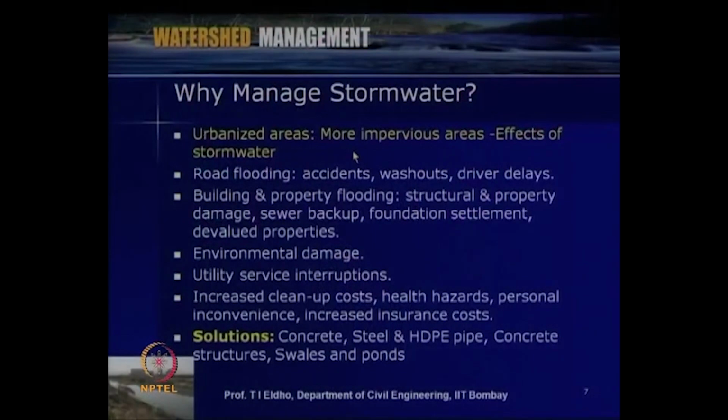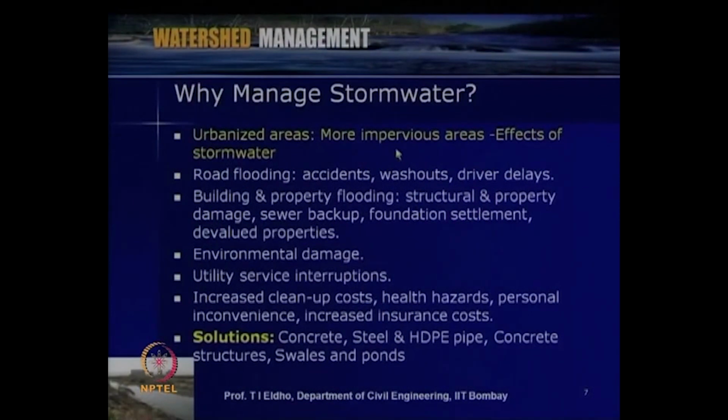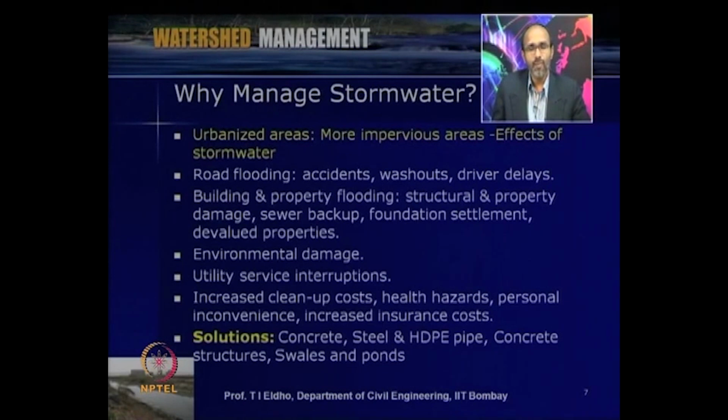So, now let us look at why we have to manage the stormwater. As I mentioned, in urbanized areas, when urbanization progresses, the impervious area also increases. That affects the stormwater. As I mentioned, the pollution problem is one aspect, and then the time of concentration and the time to peak of the hydrograph will be increased with respect to natural watersheds.